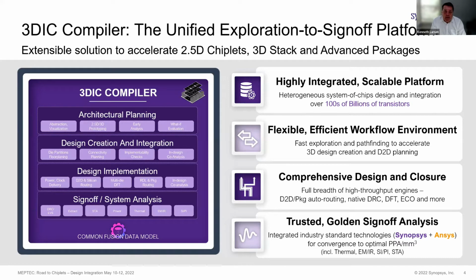Within the design implementation, I'll show some slides a little later on. We focus a lot around optimizing floor plans, ensuring correct power and clock delivery, routing of the various levels of design in the entire stack, from the individual dies all the way down to the package.